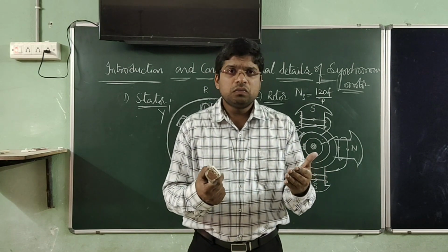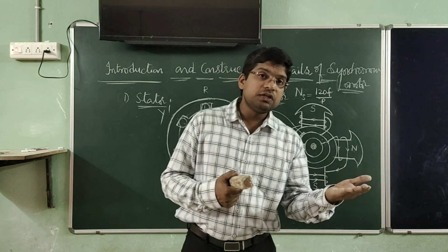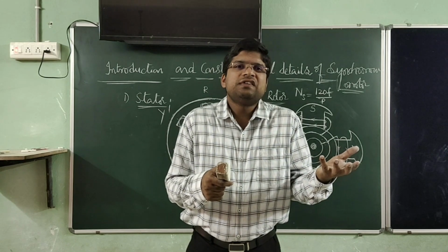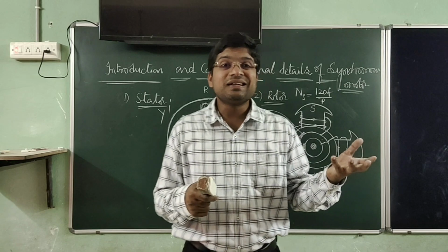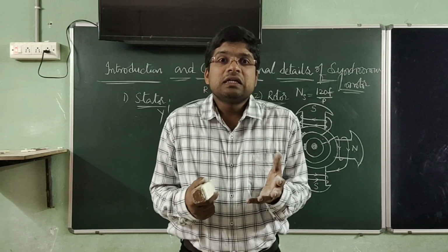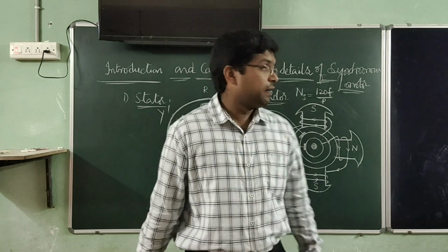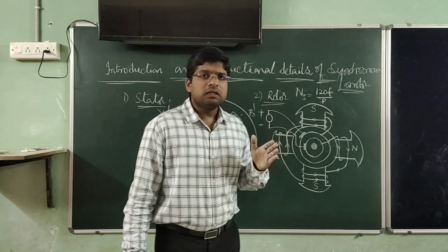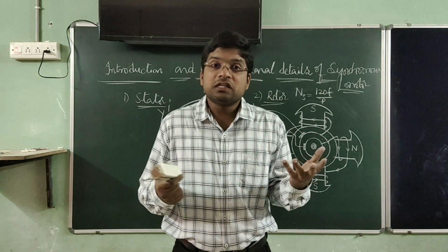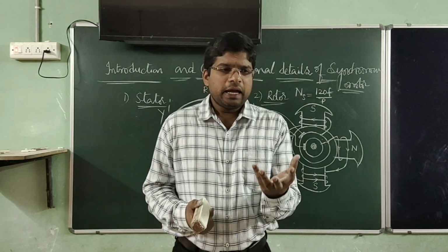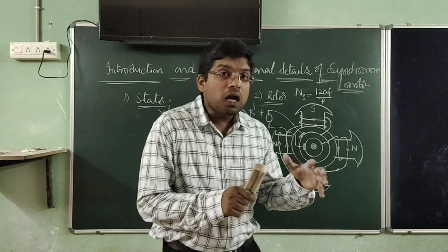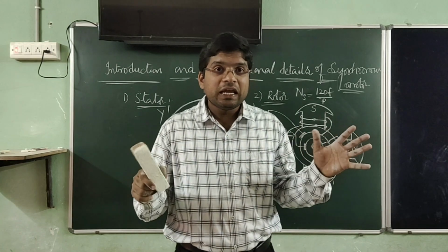Already I told you, motor is a machine which converts electrical energy into mechanical energy. In synchronous motor, we give electrical energy in the form of three-phase supply to the armature winding, otherwise stator winding of the synchronous machine. Then it gives mechanical energy at the synchronous speed. Since synchronous motor is a constant speed machine, it cannot be operated at other speeds, because usually at synchronous speed only torque is developed in synchronous motor. If the motor is not rotating at synchronous speed, then there is no production of torque.